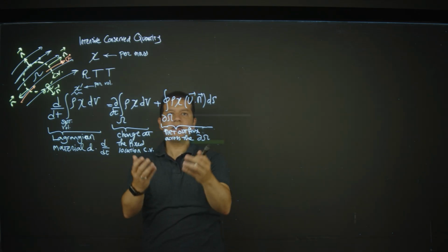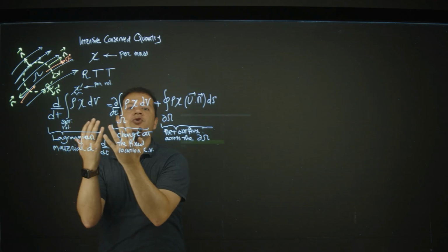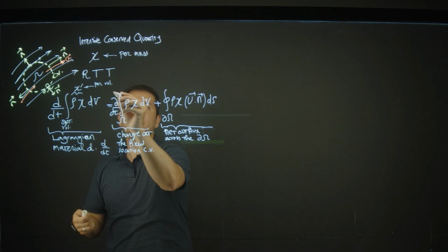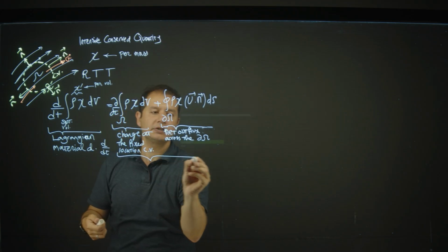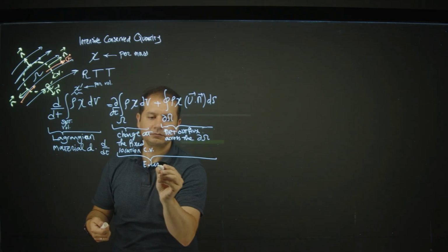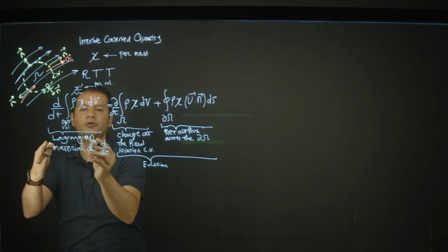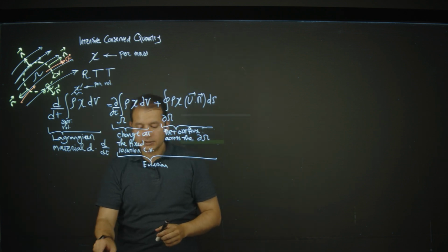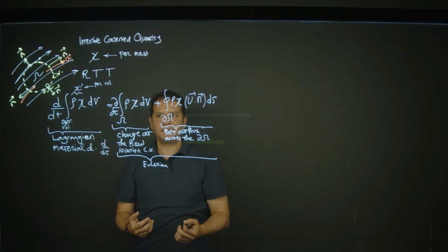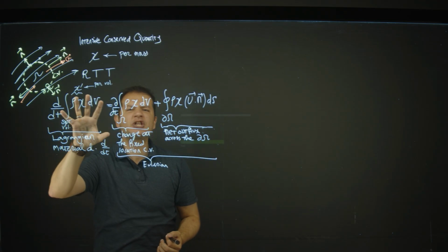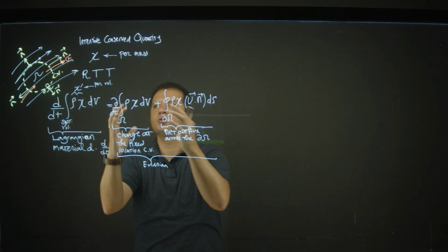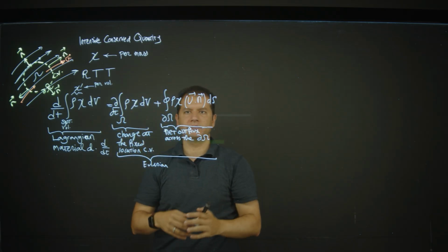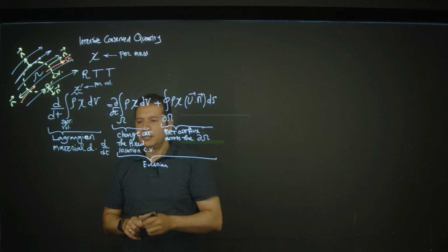This is now, in a very generic way, the translation of total material change to a fixed position change, and this is the Eulerian system. The other one is the Lagrangian system, because here you fix your position. Now I would like to write this for mass balance. This is just letting me know that the total rate of change of something is related to the fixed position control volume change of the property and the net outflux of it. So let's write it for mass balance.